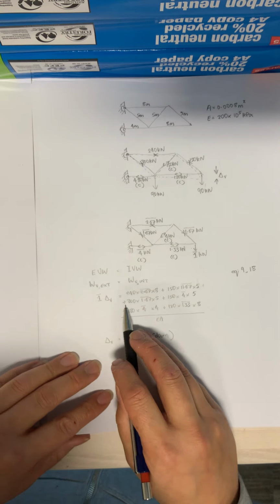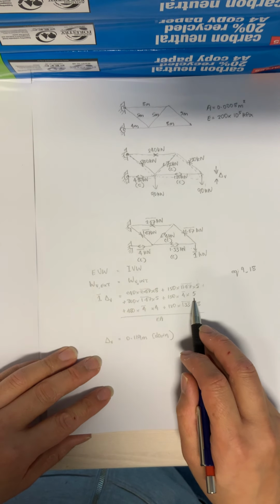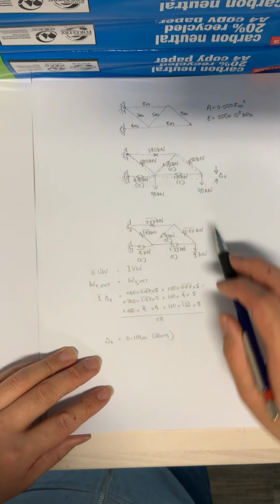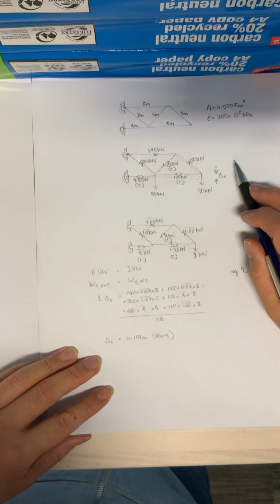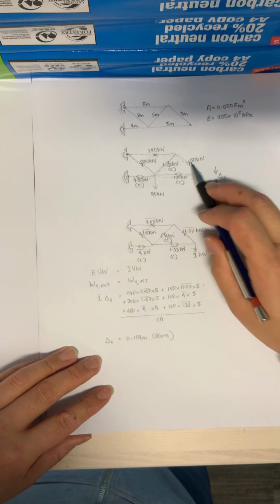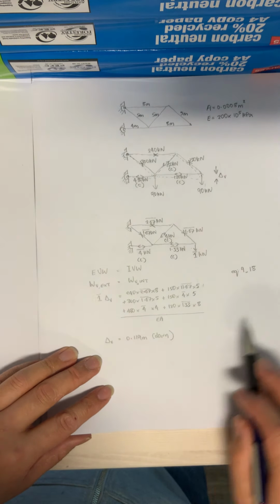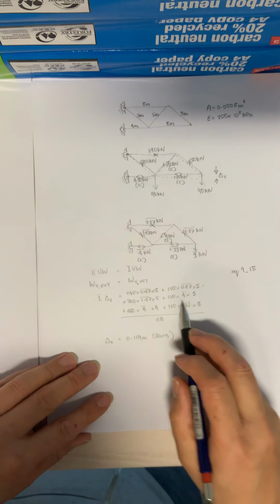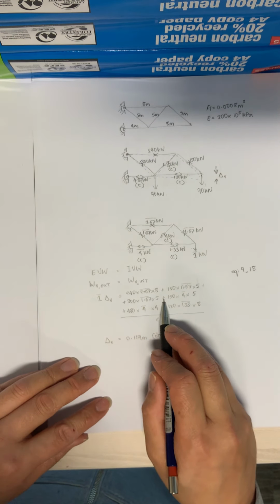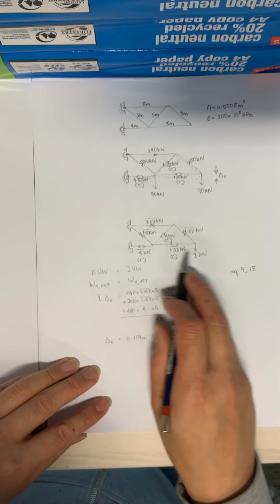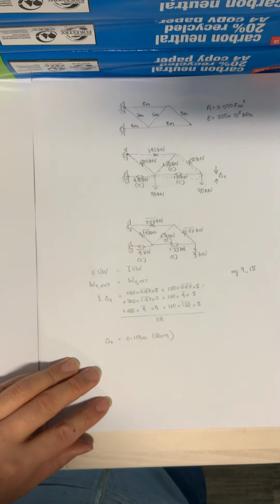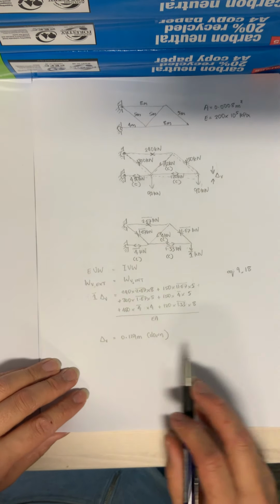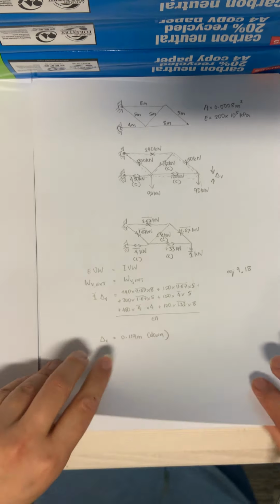So when we're doing this virtual work calculation, just remember that if the real and the virtual forces are in the same, i.e. tension and compression, then it's going to be positive, which is why everything here that you can see there has got a positive sign. And then we divide by EA, and then you get your deflection.